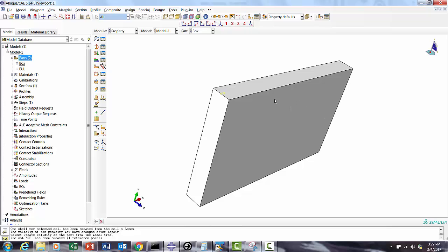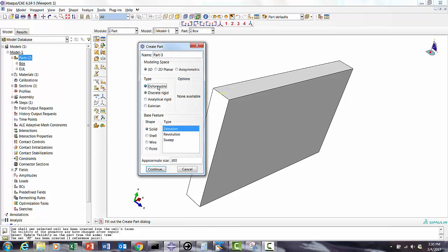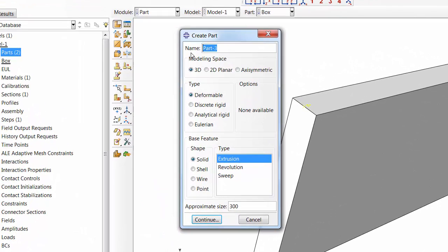So for that, we can see sloshing inside. So how are we going to fill it? We are going to fill it using a typical tool for volume fraction, but for that we need a closed volume. So we are going to create one dummy deformable. We are going to put one dummy, and then we will suppress it later.